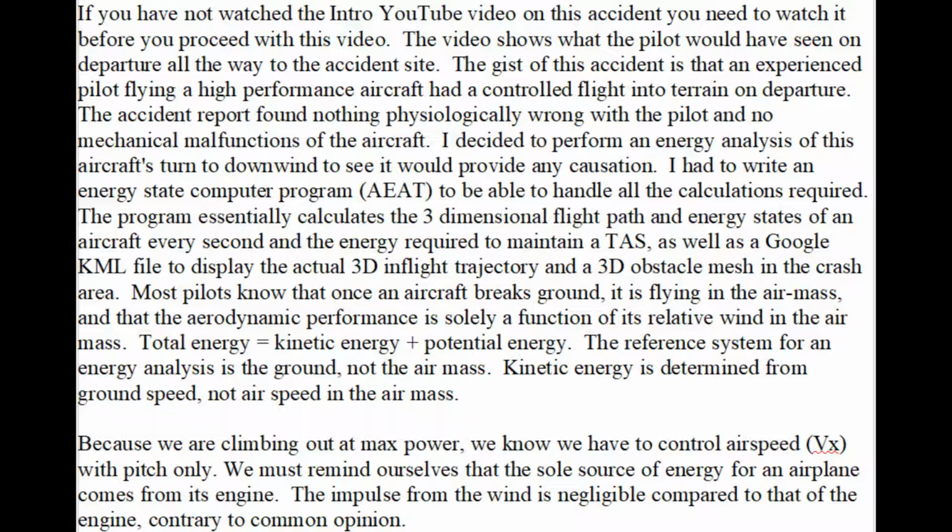Because we are climbing out at max power, we know we have to control airspeed, Vx, with pitch only. We must remind ourselves that the sole source of energy for an airplane comes from its engine. The impulse from the wind is negligible compared to that of the engine, contrary to common opinion.